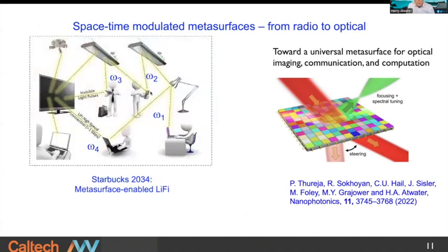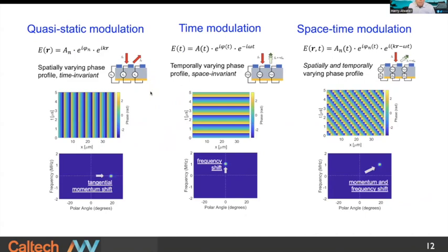Well, I'm going to somewhat provocatively suggest that one possibility is that the signal is carried not by an RF, but by an optical waveform. We can look forward to either fast modulation of LEDs, the current version of Wi-Fi, or possibly even the advent of laser lighting, as we see that laser lighting is entering in some commercial lighting fixtures. So what that means is that if we have an ability to multiplex signals onto an optical beam, we could perform the same sort of ultra-high speed wireless communication using optical beams. So let's imagine how that might happen.